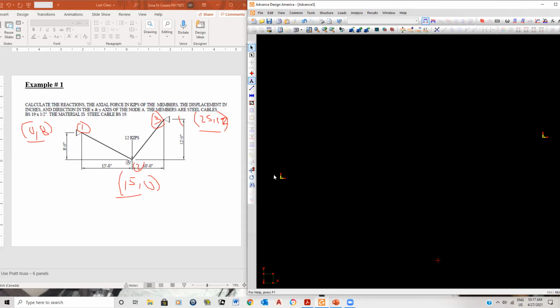So that's number one. Once I've done my nodes and modeled my reaction areas, because I like to do this systematically, because if you overlook modeling your reaction areas, your analysis will be completely off, okay? It's going to have a completely different effect on the members, and therefore all the internal forces are going to be completely different. And I think that on the last test, there was one person that did not model the supports correctly, and of course, this whole analysis for the beam was incorrect.